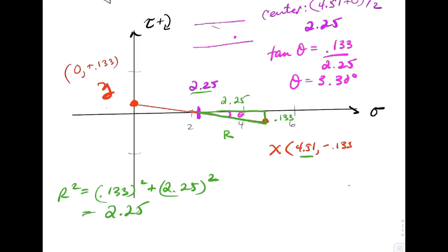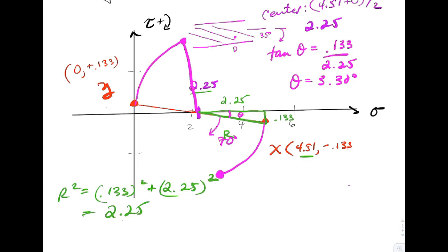There was point D. The grain of wood was about like this, and that was at 35 degrees. So what we want to do is rotate this initial stress state 70 degrees clockwise. So we're going to take this point and end it right about there. We're going to strike from initial all the way to the new of 70 degrees. As we do that, we hit movement of the y point. So that's now x prime, y prime.